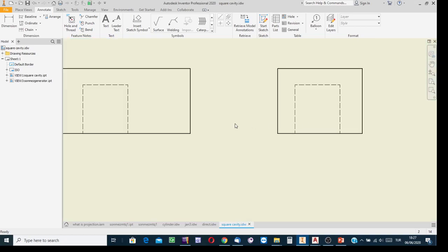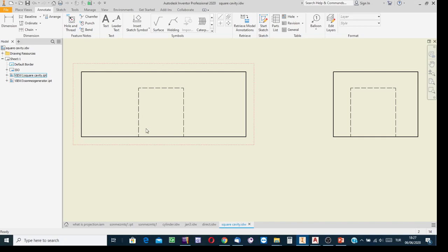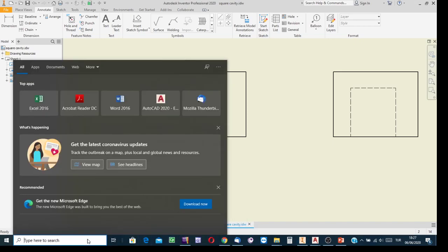But you see here on this view and the other side view, we have dash lines. You know the meaning of a dash line. In general, a dash line means the feature is hidden relative to the reader. Here we have a hidden rectangle on the front view, and for this hidden rectangle, if we follow the transfer lines, here and there, you can take a print screen and then paste it in the Paint program to draw the transfer lines.